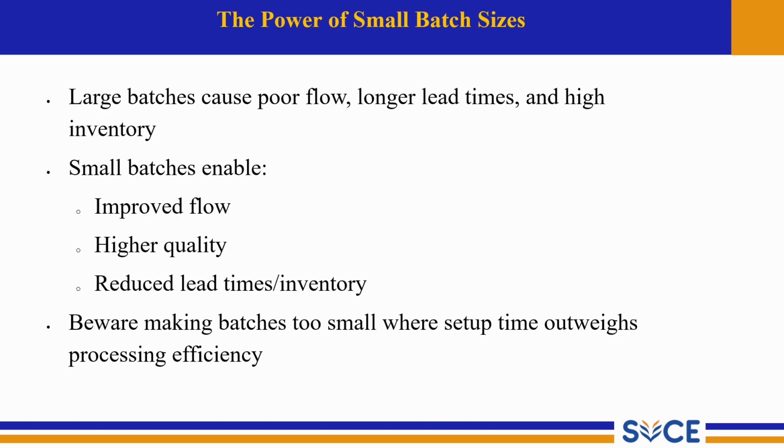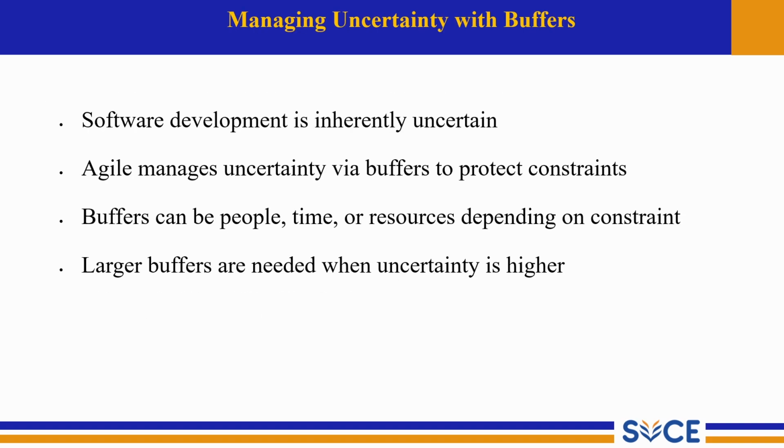The power of small batch sizes. Large batches cause poor flow, longer lead times and high inventory. Small batches enable improved flow, higher quality, and reduced lead times and inventory. But avoid making batches too small, where setup time outweighs processing efficiency. And next one is managing uncertainty with buffers.